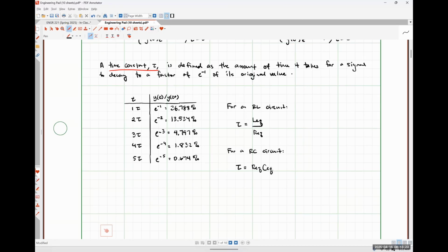Step three was analyzing the circuit at t is equal to infinity. What we're dealing with today, that is no longer going to be just everything is 0. So this is going to be an important part of our process. Step four was calculate LEQ and CEQ, or excuse me, LEQ and REQ, or CEQ and REQ. I'm now going to call step four, calculate the time constant for the system, which inherently requires us to calculate REQ and CEQ as well. Okay. And then step five is once again just going to be plug everything in.